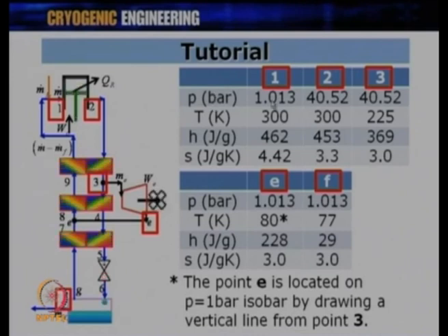So, different properties in terms of entropy and enthalpy, this is the most important part. If you commit any mistake on this, then the whole problem is going to go wrong. So, one should always have the habit of locating points 1, 2, 3, E and F, and correspondingly one should correctly write the value of enthalpy and entropy. This is a very common mistake students commit, because they read the TS diagram very fast, the correct points are not located, and sometimes your yield also happens to be negative and things like that. So, the enthalpy and entropy values have to be correctly taken from the TS diagram.